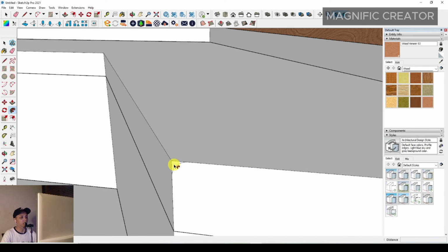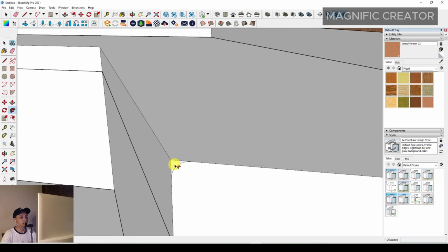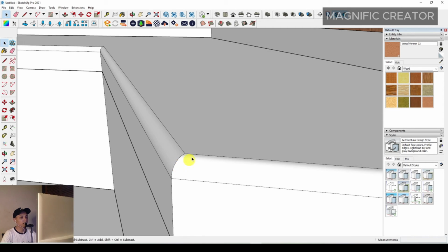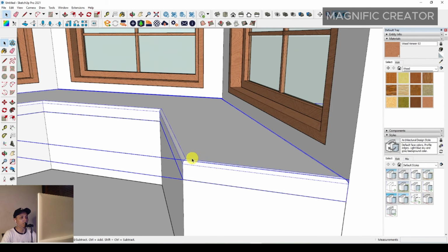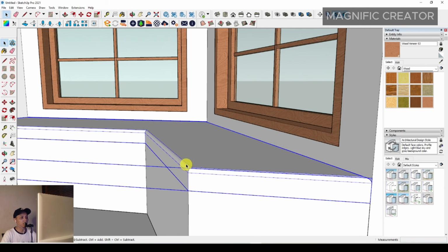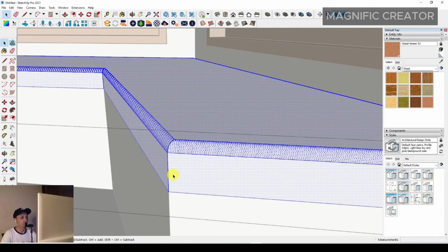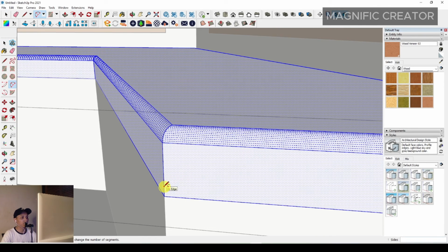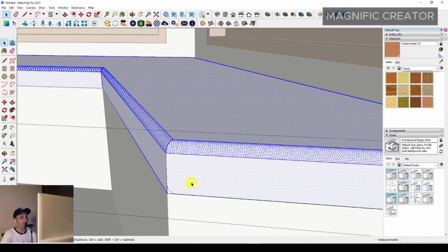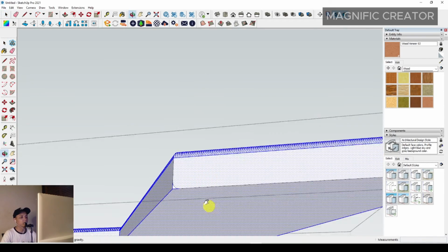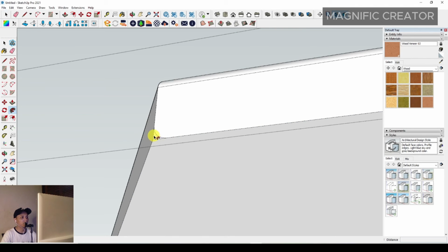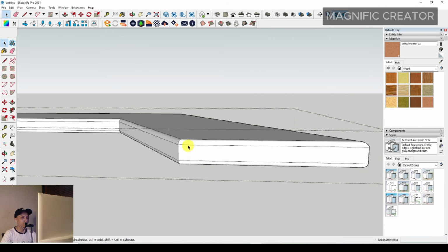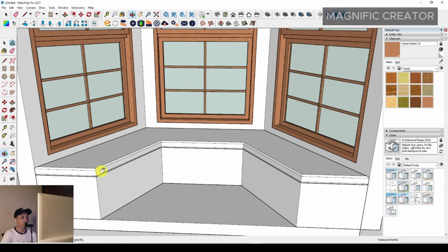this corner shape of the arc, and then you have to make it group anyway. You have to make it group, and you can make the 2-point arc again on this bottom side, and you can do the same method as before. Then you can just click the plane and select the follow me, and just select this corner area, right? So you can see the smoothness of this cushion area.